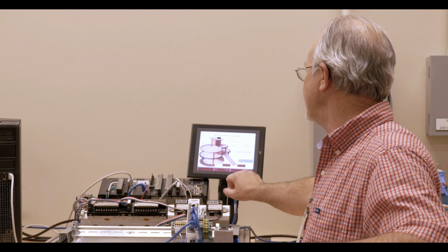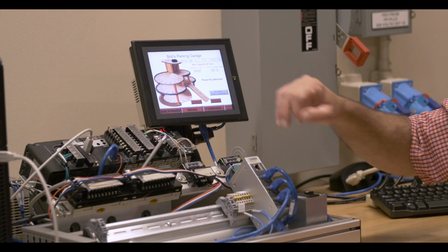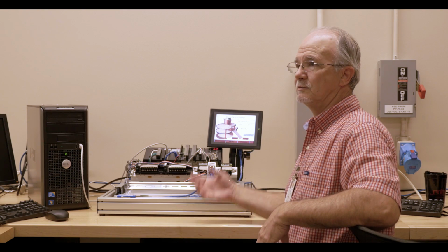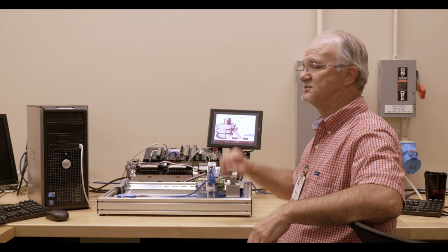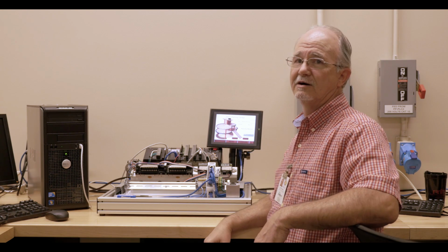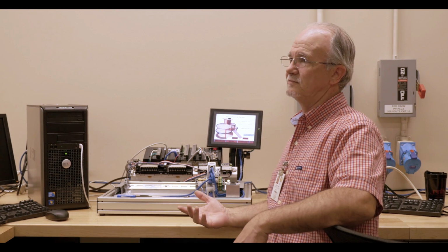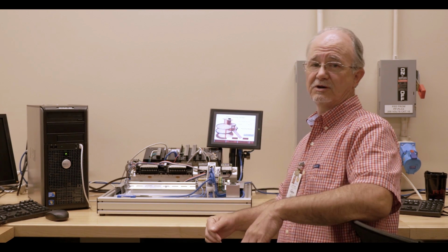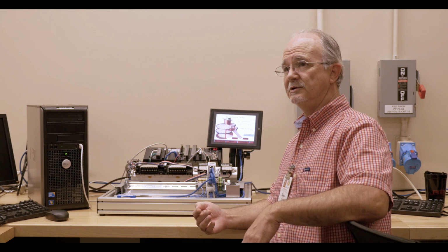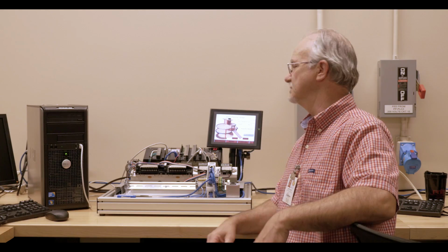They go through and they write their program. They have to put their limits in to be sure that it will not go negative. When the value in the lot here is at zero, the car leaves button is held in a non-functional state, so it will not function to subtract one from the number. By the same token, if the lot's full, we do not allow the car enters button to actually function.